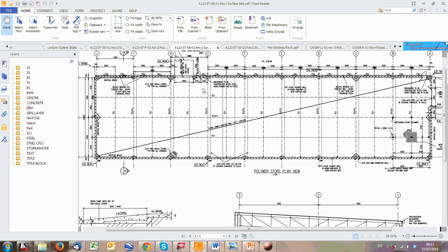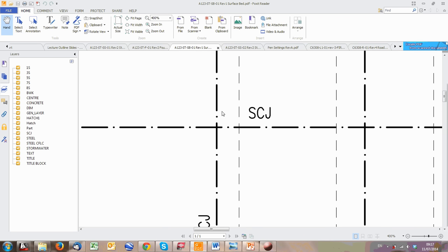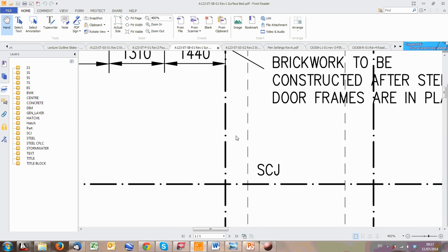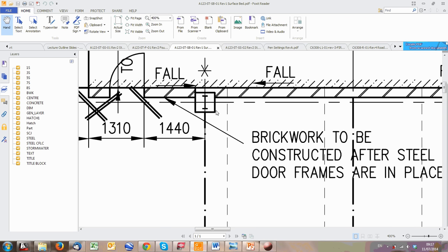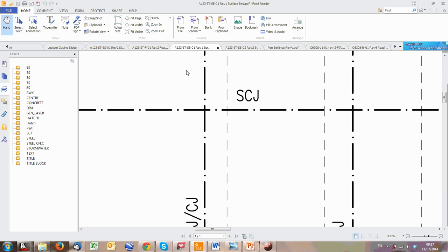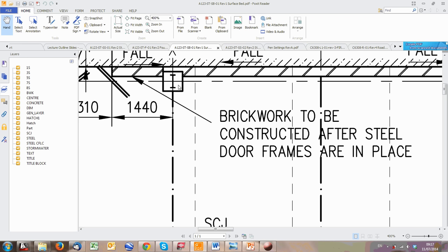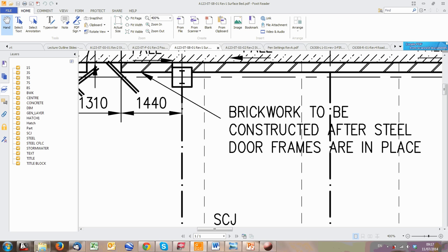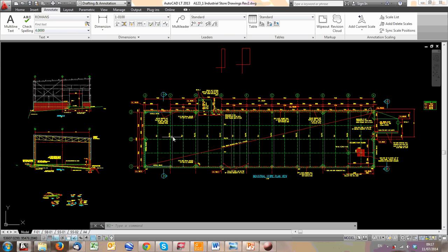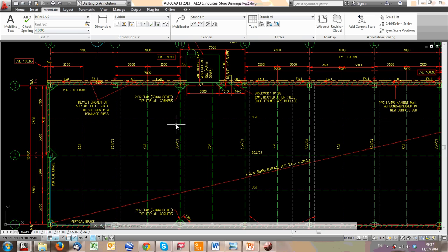But to make a drawing clear, you have thick lines and you have thin lines. For instance, I've zoomed in on this drawing. You'll see some lines are thinner, some lines are thicker. And by using different line thicknesses, you can produce a drawing which becomes clear. And you do that by using certain colors and mapping those colors to a thickness.